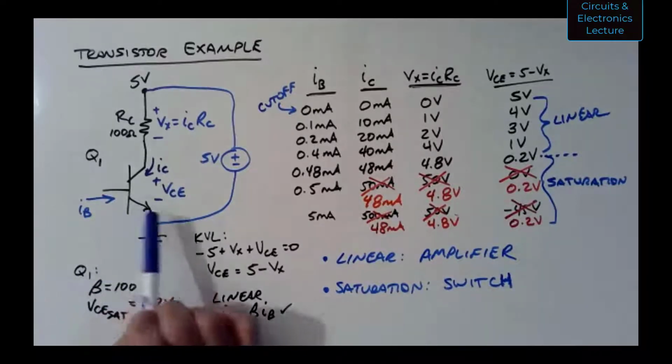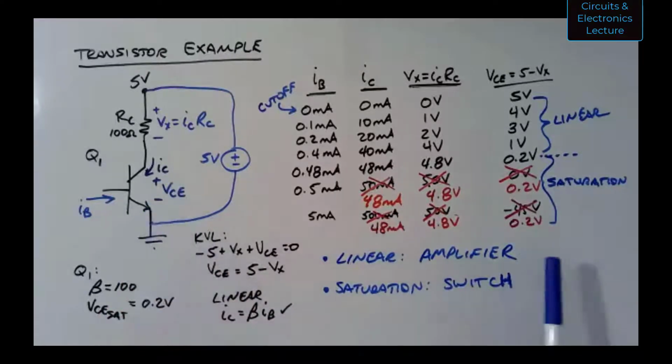That voltage where that happens is where VCE is about 0.1 to 0.2 volts, somewhere in there. But we usually use 0.2 volts as an approximation for design purposes and analysis purposes. And it gets you pretty close. Does that answer your question? Yes, thank you. And it looks like a question just popped up in the chat about it too.